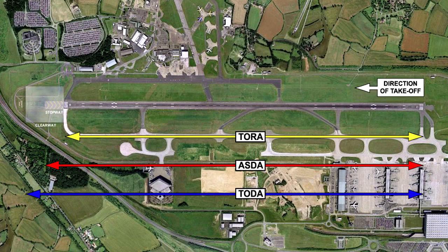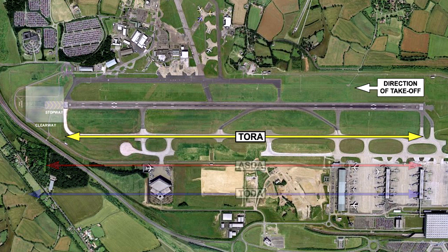If you remember, airfields can have different lengths of takeoff run, takeoff distance, and accelerate stop distance, as shown. Therefore, there should be many mass graphs. There should be a mass graph for ensuring that the mass is such that the takeoff run required is within the takeoff run available, that the takeoff distance required is within the takeoff distance available, and lastly another mass to ensure the aeroplane's accelerate stop distance required is within the accelerate stop distance available.